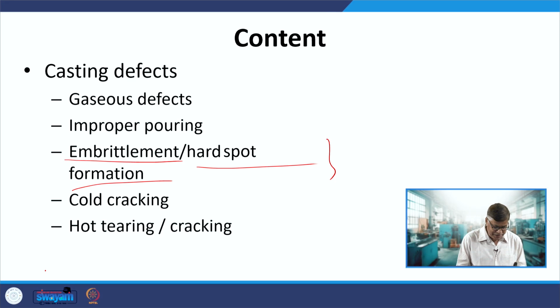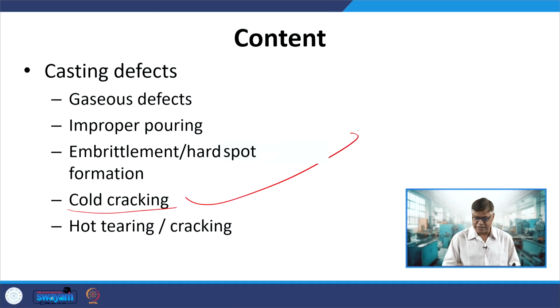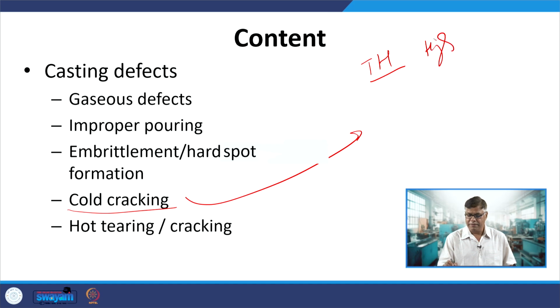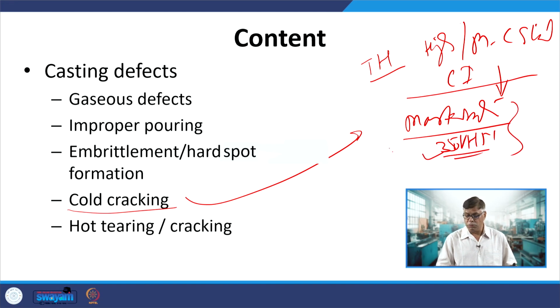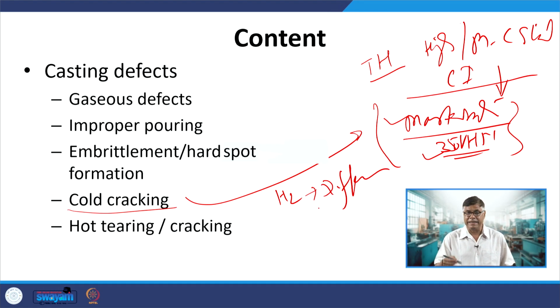Another major metallurgical issue encountered in castings is also observed in the case of transformation hardenable metals, say high or medium carbon steels or cast irons. Whenever these are cooled rapidly and form a martensitic structure coupled with a hardness of greater than 350 VHN, and the casting conditions are unfavorable with regard to hydrogen, hydrogen gets diffused in the molten metal and is then retained in the casting.